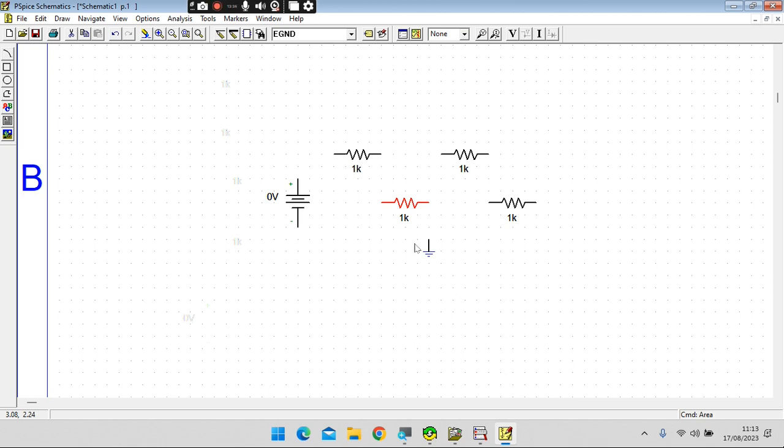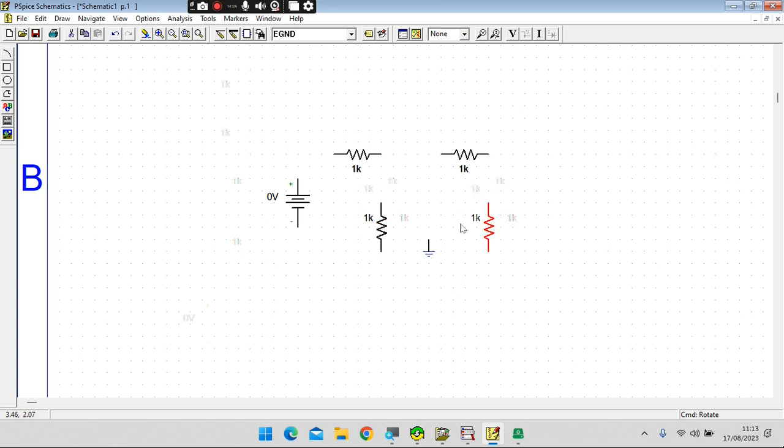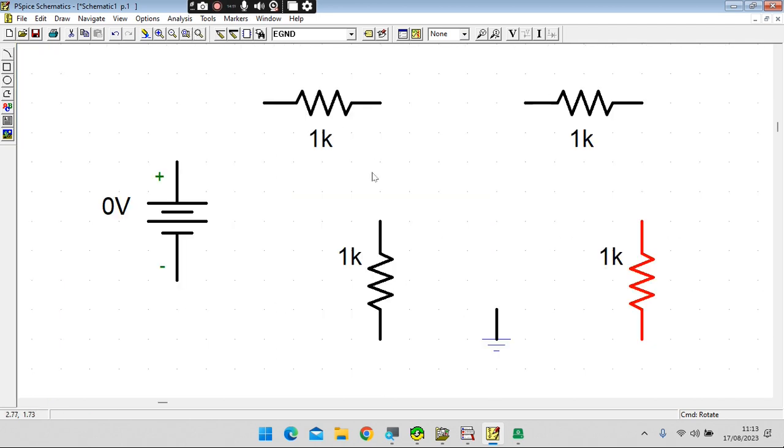All that you explore. I'm not giving you the details of each and every thing we explored. We explored in the same manner. You also try. So now Control F to flip, Control R to rotate. Select the components and press Control R. You can see Control R means it will rotate. Select this one, Control R to rotate. Now you click on this, so it will fit into the screen. Yes, yes, I'm observing.